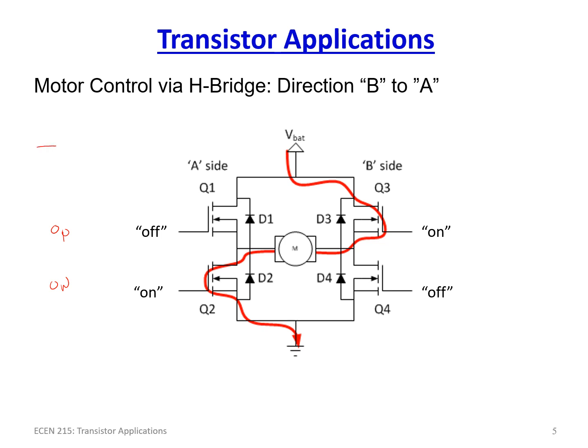And you have to really pay attention to the fact that if in time this is the A control and this is the B control, if A is doing this and then B is going to turn on, ideally you would want to turn on right here, but if there's a slight overlap where this stayed on even briefly, then right in this section here, this would be a short. So that's something that is vitally important when you're designing anything with an H-bridge to make sure that doesn't occur.